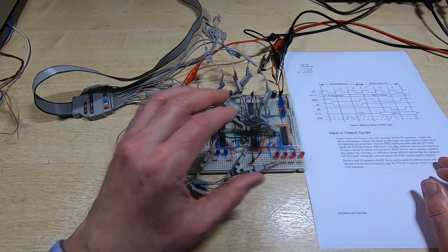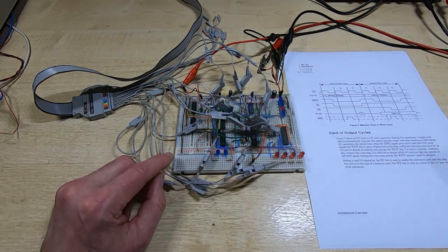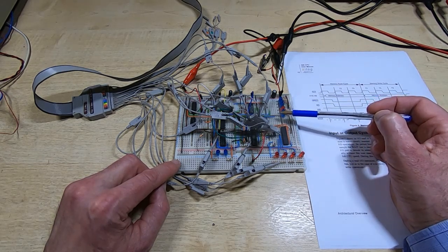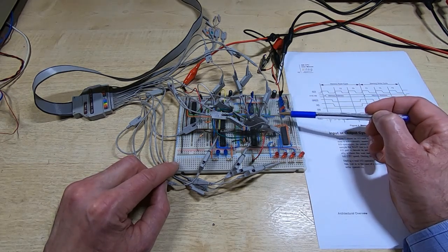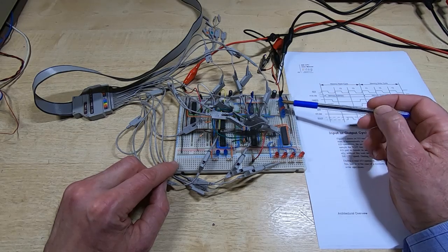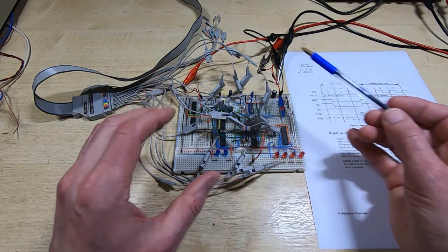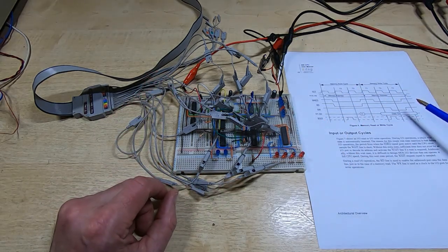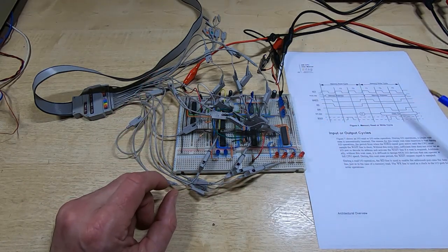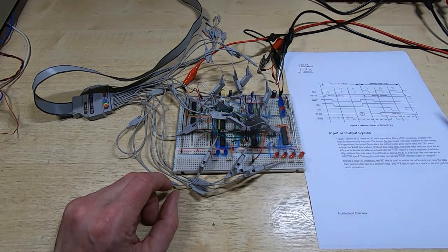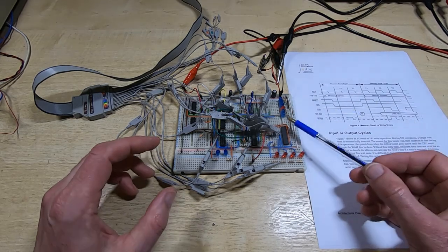This circuit does several other things as well, because we still need to be able to access the floppy drive controller directly using in-out instructions, so we can actually load it. The DMA only takes over once the transfer from the floppy drive controller starts, but we still have to load up the parameters into the floppy drive controller beforehand to tell it what we want it to do.